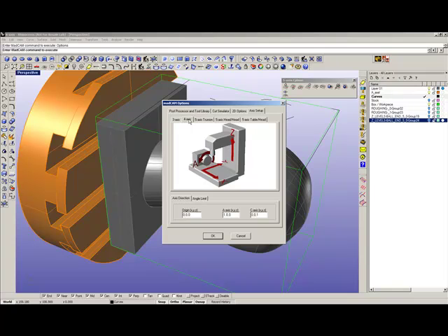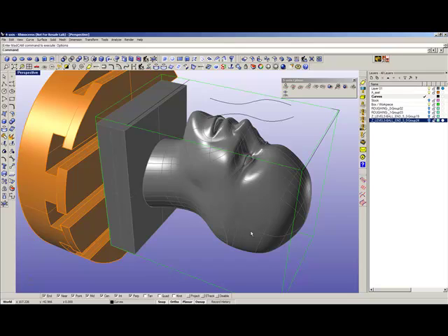If we select the 4-axis, we have a rotation table, and we can set the direction of the A-axis, and the direction is a vector for x, y and z. So 1, 0, 0 will set the A-axis to rotate around the x-axis. Then it's just to click OK.